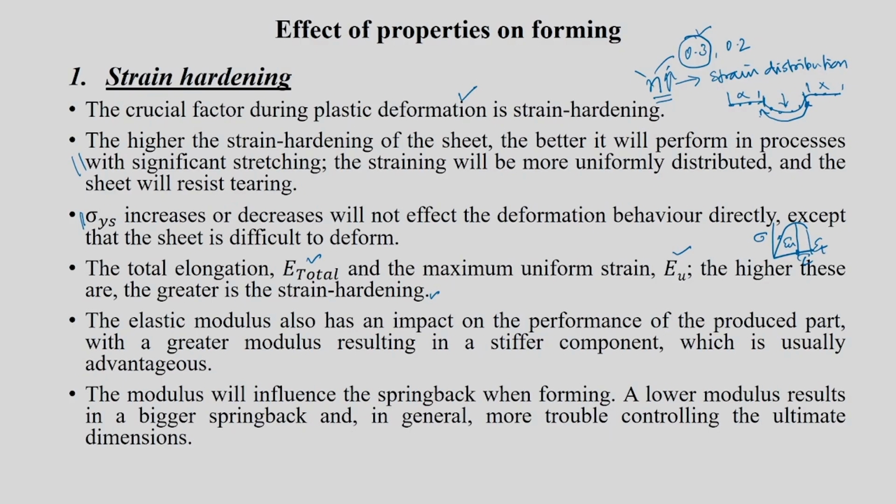You may say that if the n value is larger, then epsilon u, where the UTS is reached or instability starts, will also be a little larger. So your necking is actually delayed.